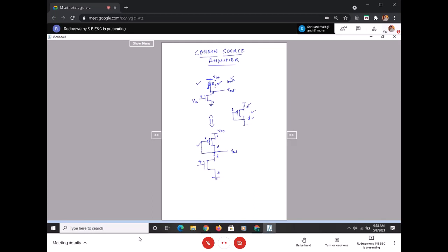Okay, exactly. That's why I asked you. I told you, when VDD is fixed and R is fixed, what is the current that is flowing through RD? Now, when can I make this PMOS transistor, which is now acting as a diode, give the constant current? Under forward bias, under what region of operation should this transistor be in order to pass or allow the constant current through it?